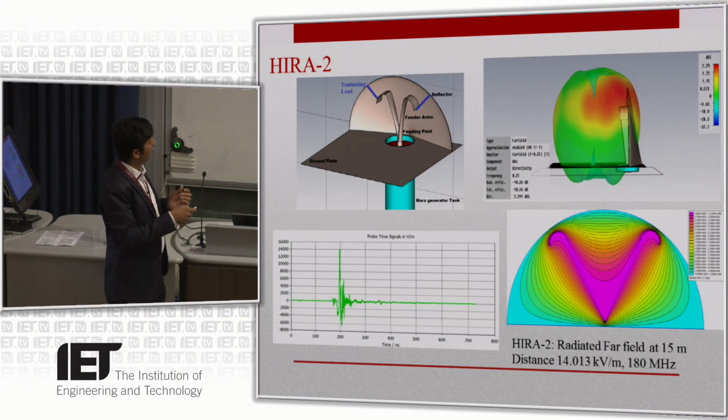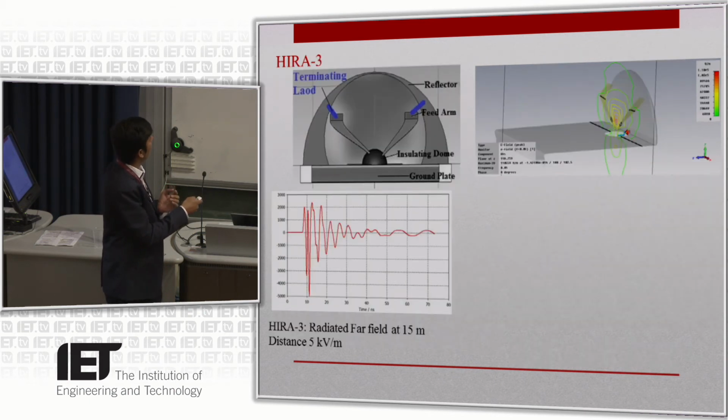This improvement is mainly because of this folded feed nature, and there is also a launching angle, called beta. This launching angle is very important, because we are launching, feeding the pulse to the arm and terminating it with a matched load termination. It's about 180 ohm. That's why the arm nature is there, and the uniform field distribution, called fill factor, we improved by a 1.2 factor. So it is directly affecting the electric field intensity, about 14.4 kV. This is the improved electric field intensity.